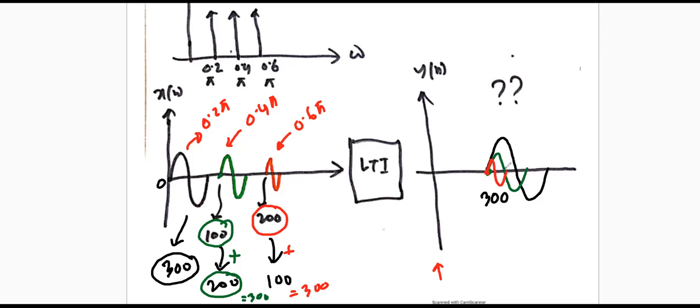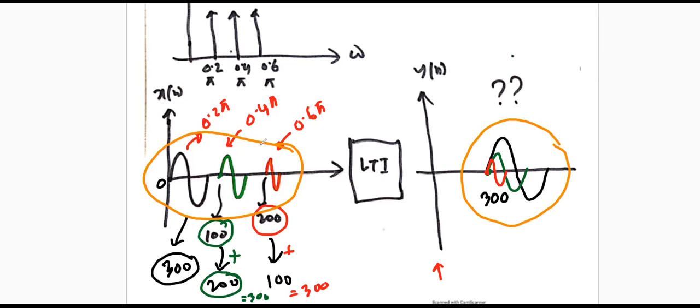It's a higher frequency. Now we can see that it makes a lot of problem, isn't it? You can't retrieve your actual signal. The actual output should be like this: higher frequency, then lower frequency, and then lower frequency. It should be shifted, as we have shown in the earlier example. However, because of the non-linearity of the phase, we have found this kind of issue. So how can we solve this?